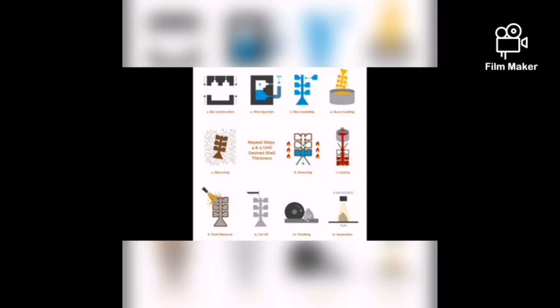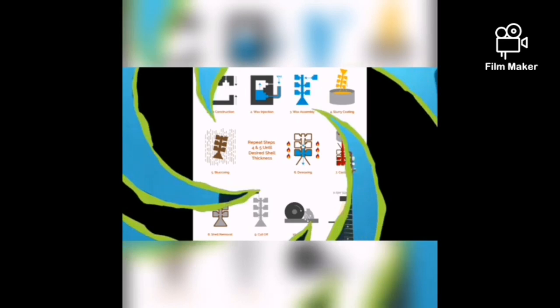And then the finishing process is grinding, sandblasting and coating to achieve the final surface needed. And once the finishing operations are done, the parts are inspected for surface and subsurface defects. Visual and fluorescent penetrant inspection is done for surface defects and X-ray is employed for subsurface defect identification.